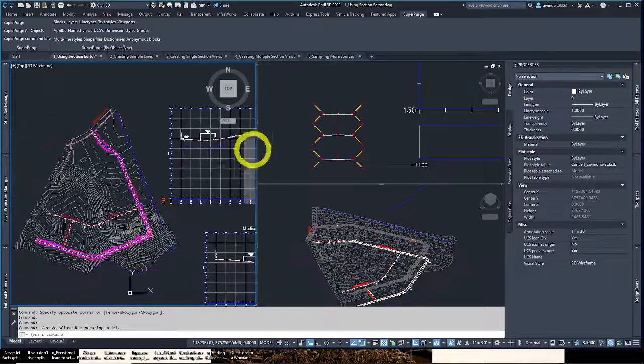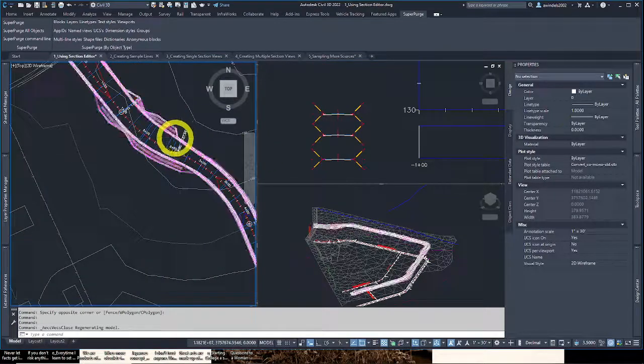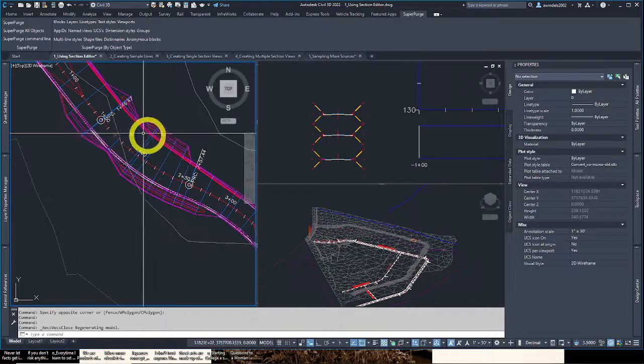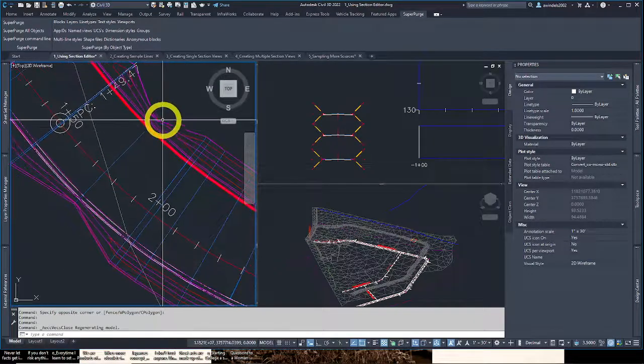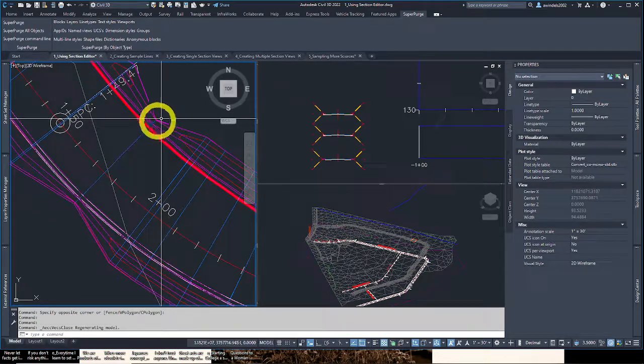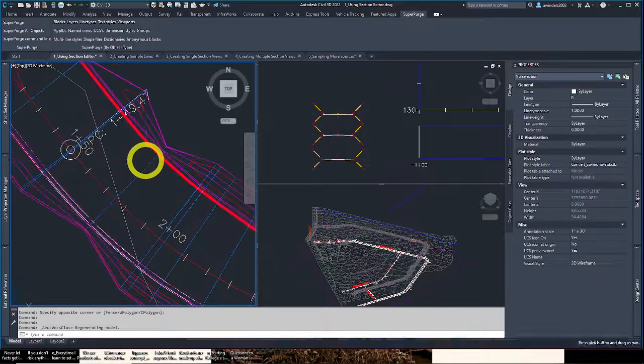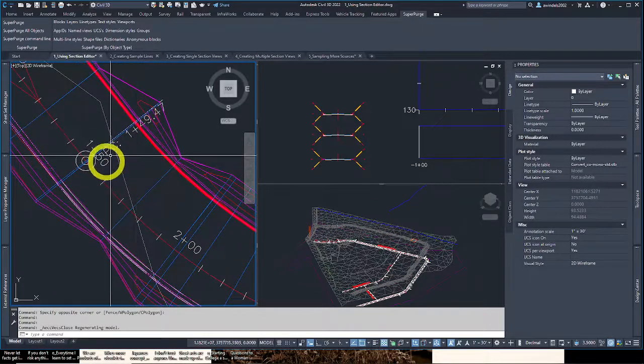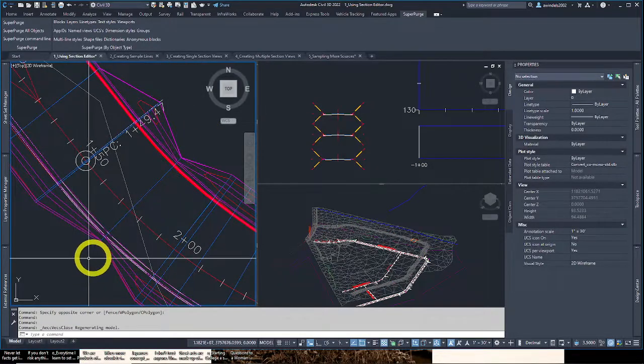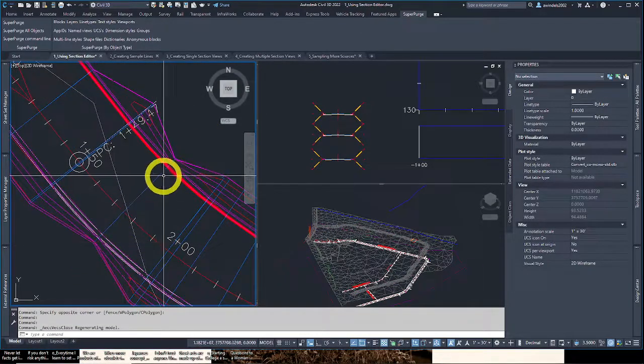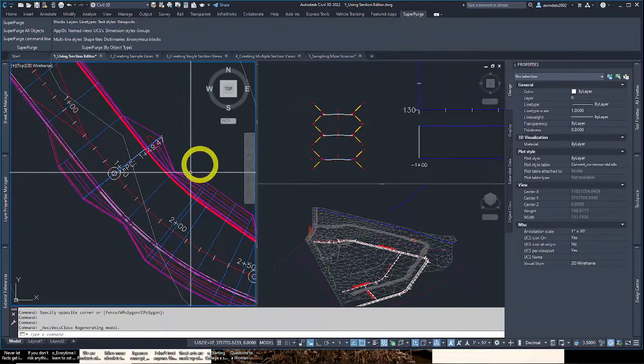It wants us to zoom into where the ditch is at 175. You notice what we edited, we told the ditch to go away. Essentially we shrunk it down here, and you can see what we did in plan view here. It's essentially nearly gone. It's just cutting into the earth a little bit more sharply. That's where we made our edits.